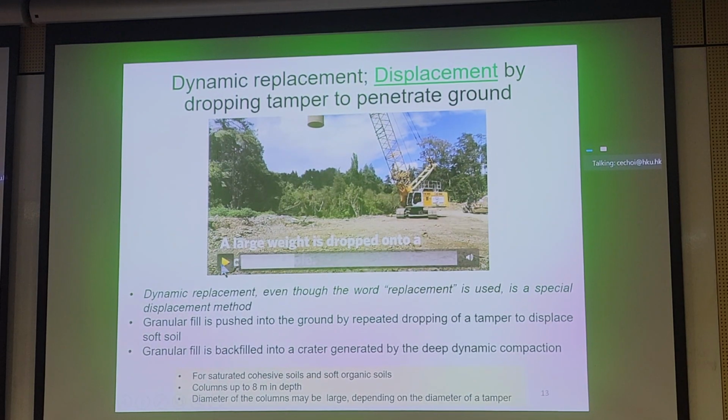Now, evidently, you need a pretty large hole to be able to drop this consistently into the hole. And to drop it cleanly into the hole, you probably cannot have very deep improvement depth, right? So that means your marine deposit or clay layer cannot be too thick. And this is probably quite disruptive environmentally, and there's more safety protocols, because every time you drop this, you'll have a very significant PPV, or peak particle velocity, or vibration in the ground.